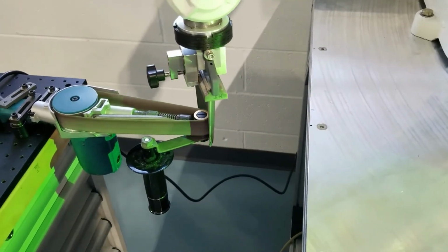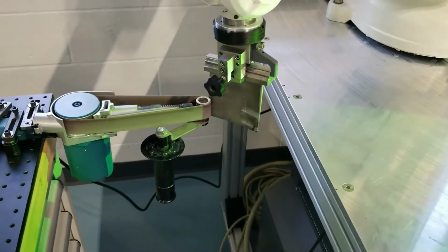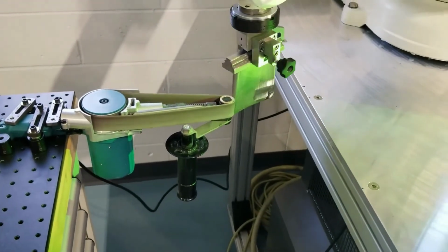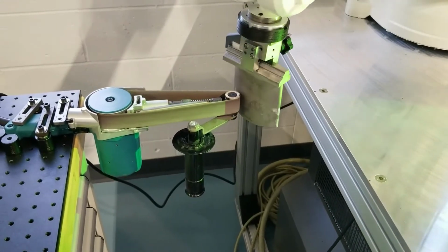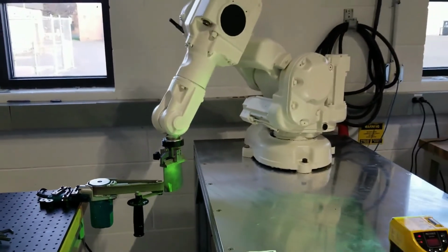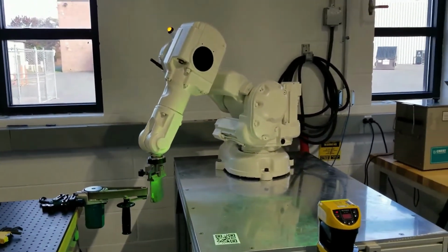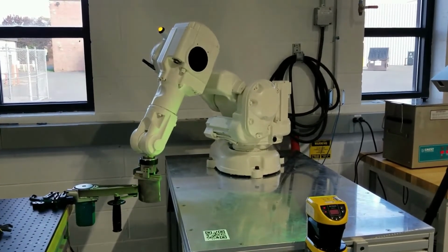And so Sam went through a welding process to add material onto the trailing edge of this particular blade. And so this is where this video starts off. And we're going through the first iteration of grinding down that positive material that was added to get it to the nominal state.